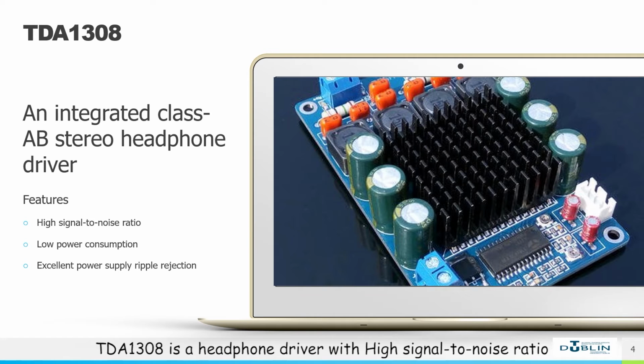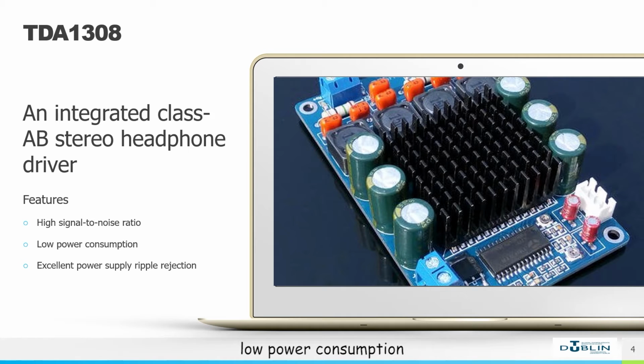TDA1308 is a headphone driver with high signal-to-noise ratio, low power consumption, and excellent power supply ripple rejection. It is used to connect the microprocessor and audio output jack. It raises the low voltage signal from the microprocessor to a sufficient level so that it can be converted into sound waves by the speaker.